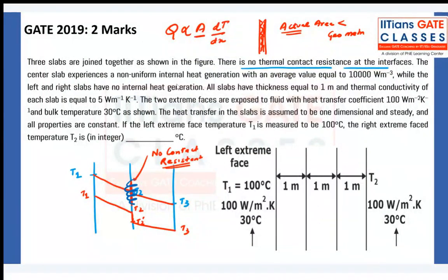What is the second reason? Because there are voids, air will enter into these voids. Now thermal conductivity of air is less than thermal conductivity of the solid body. And because thermal conductivity is less, again, less heat transfer will happen. And that is the reason, if these two conditions are significant, then the contact resistance will be significant. Is it clear? The concept of contact resistance is clear or not?